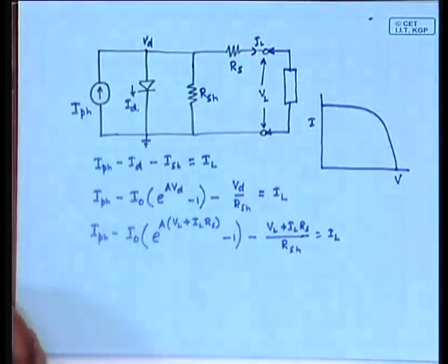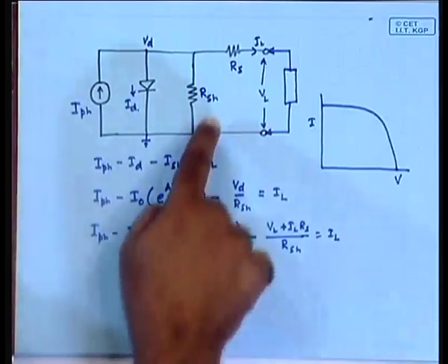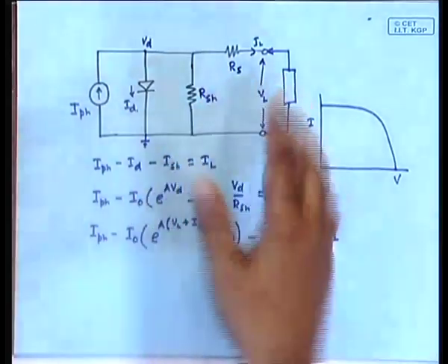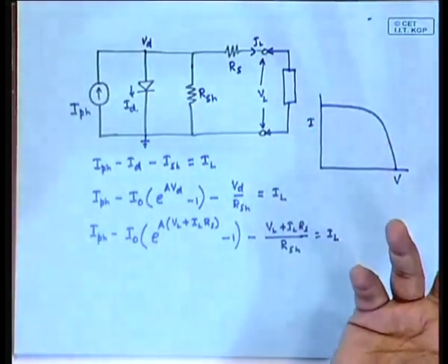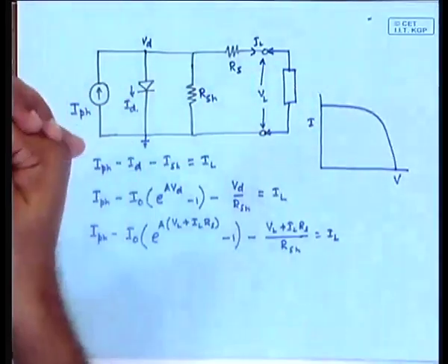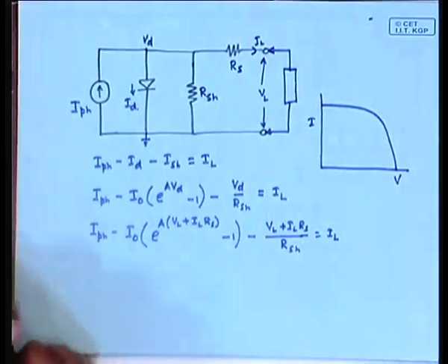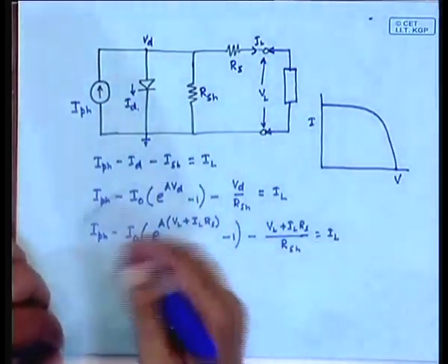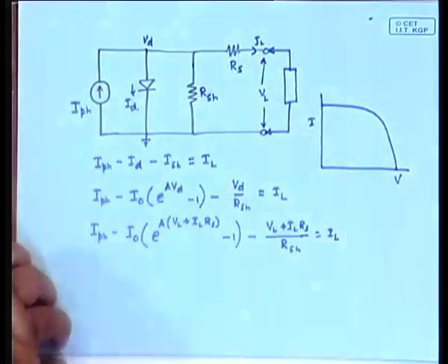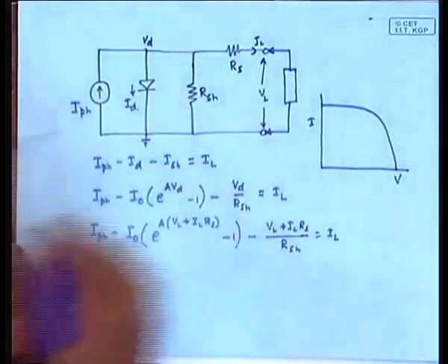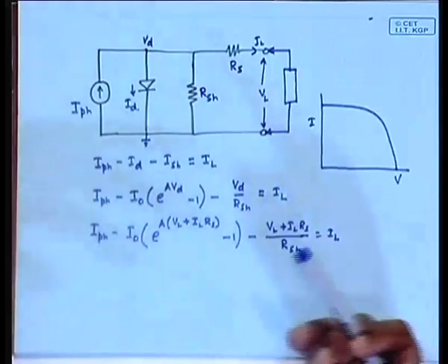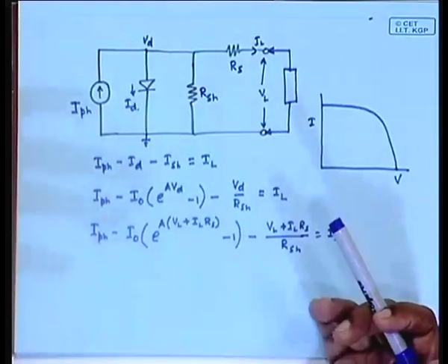What will be the effect as seen in the equivalent circuit? It will be reduction in RSH. Why? Because that increases the recombination. The amount of charges that were separated, before they can pass through the load, they recombine because of the shorting. So, with age the series resistance goes up, the shunt resistance goes down, and as a result the efficiency of the cell goes down.